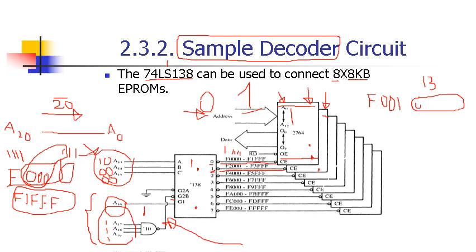So you need this 0 to make the hexadecimal conversion. Your beginning address would be F2, then 12 zeros. For your ending address, you make these 13 zeros 13 ones. Again, this would be 1. You get the conversion of this final address as F3, then the other 12 ones. Alright, here you are, and so on.